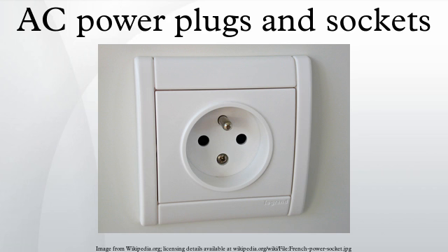Also, as in some countries electricity was supplied on a split tariff basis with electricity for lighting being charged at a lower rate than that for other purposes, lamp holder plugs enabled consumers to reduce their electricity costs and were thus in broad use. Lamp holder plugs were and are rarely fused. In the UK, lighting circuits are protected with a 5A or 6A fuse or circuit breaker. Wiring regulations in the UK and some other countries no longer approve lamp holder plugs because of the risks of overheating and fire. Edison screw lamp holder adapters are still easily found and commonly used in the Americas.